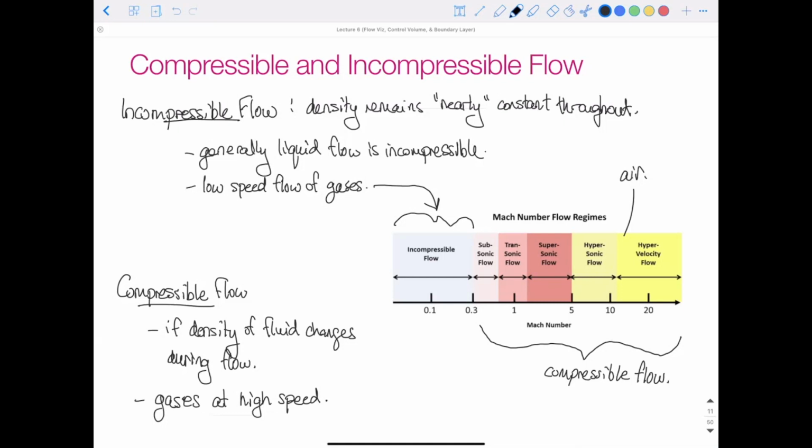So yeah, hopefully to answer your question, Adam, is compressible flow possible with liquids? For any practical application, no, when we're just dealing with flow. If we're dealing with other properties of fluid, maybe we're sending shock waves or ultrasound, maybe we wouldn't consider the compressibility in that case, but for the realm of material in this course, we'll generally consider that liquids are incompressible, or the liquid flow is incompressible.